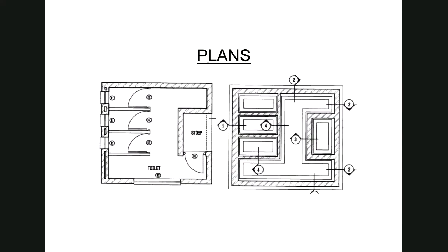Okay, so just before we dive into the example, for those of you that did not do your preparation, let me just remind you that for the cavity wall, the one brick wall all around, so in other words, details 1, 2, and 3 over there, we have cavity wall in superstructure. We have 330 millimeter wall in foundation. And similarly for the one brick wall, we have 220 in superstructure and we have 330 in the foundation.